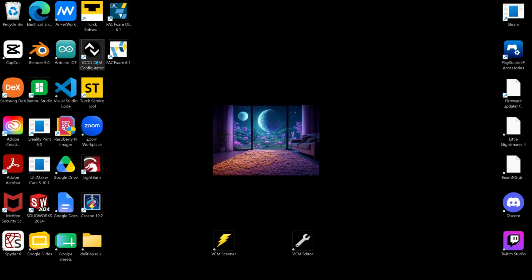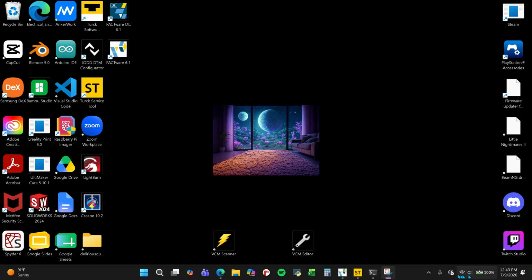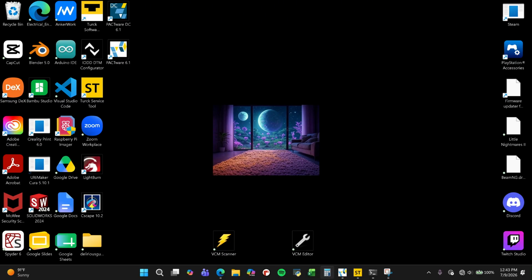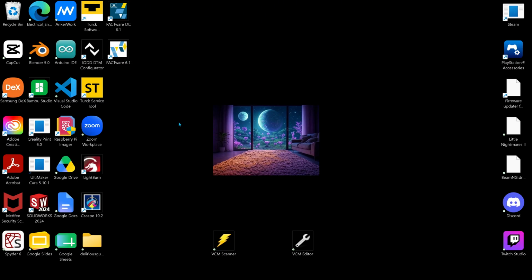Okay. The next thing that we're going to do is open up this PACTware software or application. Another thing to note, I'm going to go ahead and shut off my Wi-Fi, because that is a communication method, and I don't want this to get confused whenever I'm trying to only communicate through the Ethernet. So you might have to do that. So we're going to go ahead and open up this PACTware 6.1, not to be confused with the DC version. That's not the one we're using. It is the regular one.